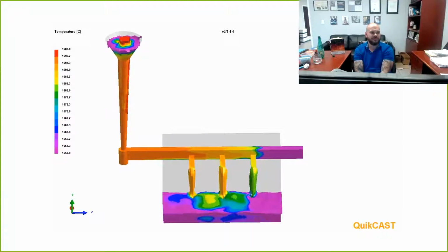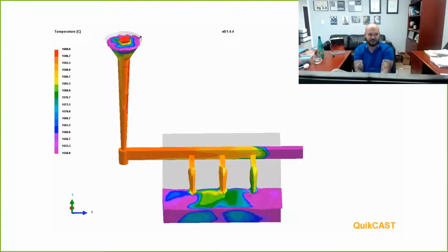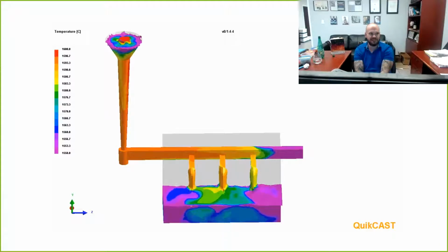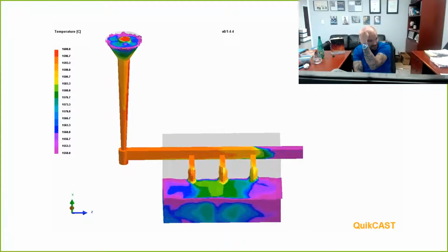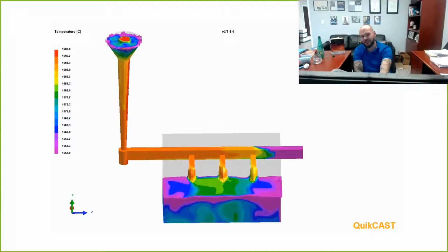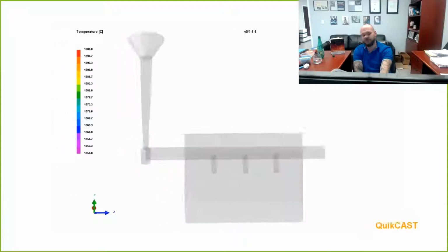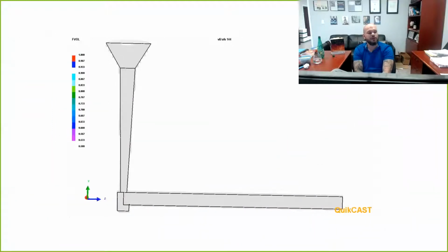Now, that temperature fluctuation within the sprue itself is clearly because we've got some volumetric displacement issues, right? If this whole thing was completely full, we'd expect to see that temperature gradient being nominally exactly the same. So let's take a look at this exact same simulation. We'll slice it longitudinally down the center and change the viewport to fluid volume. In this version, everything that's red is metal, and everything else that's not red is a combination of air and molten metal at various stages.